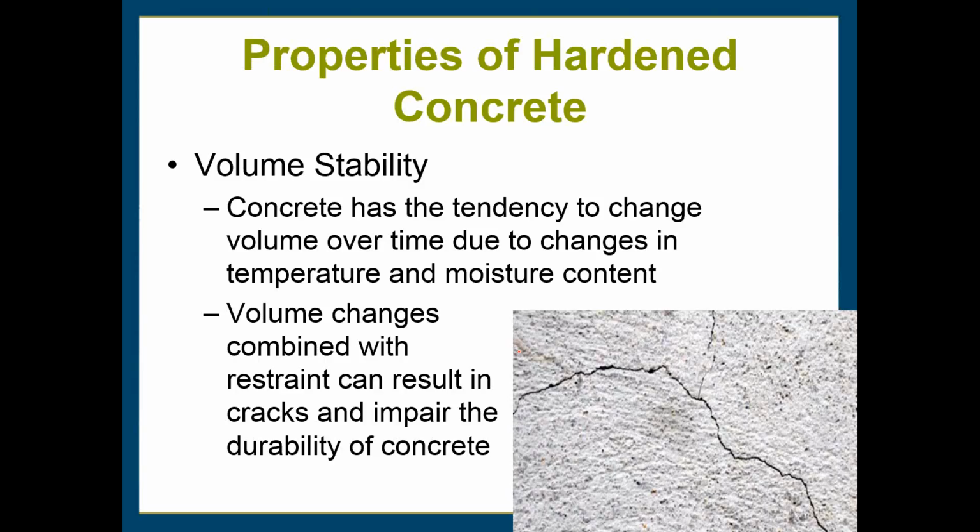So concrete has a tendency to change volume over time due to its ambient temperature and moisture surrounding it. Combined with those volume changes, restraint like rebar can also result in cracks and impair the durability. I don't feel like that's as big of an issue, though. So, Claude, do you have anything to add about that?